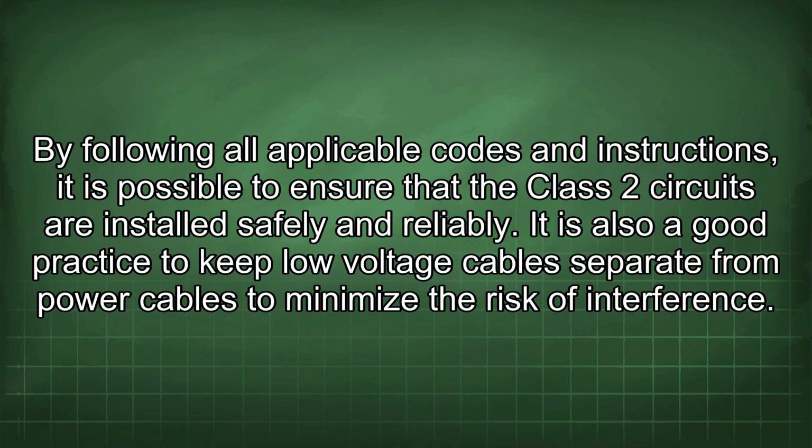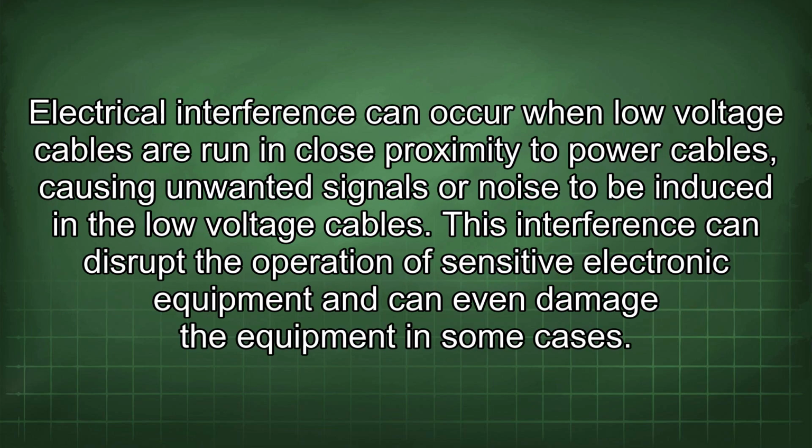and reliably. It is also a good practice to keep low voltage cables separate from power cables to minimize the risk of interference. Electrical interference can occur when low voltage cables are run in close proximity to power cables, causing unwanted signals or noise to be induced in the low voltage cables. This interference can disrupt the operation of sensitive electronic equipment and can even damage the equipment in some cases.